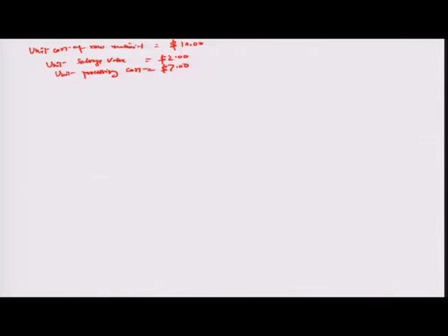And we already know that there is only the j equal to 1 option available, because they have made up their mind on the turret lathe. They do not have any flexibility on the change of specification. It has already been designed by the design department and given as the only option. So, j is 1 in this case, and we assume a tolerance to be produced in this shaft as an engineering requirement from the design of 1 plus minus 0.003. So, as you have already seen, the mu j value found by the manufacturing engineering in the turret lathe is about 1.00 inches, and the sigma j value of the turret lathe is 0.003 inches.